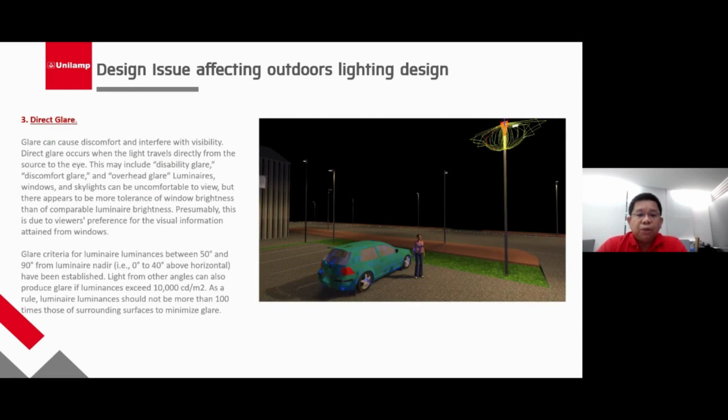This is one of the dilemmas when we are designing outdoor lighting fixtures. We should know the proper distributions, probably below 60 degrees, so that it doesn't give more than 60 degrees of distribution, in order to limit the glare. Like for flood lighting, when you design area lighting or flood lighting, you need to limit the maximum tilt below 60 degrees. Otherwise, it will create some glare.